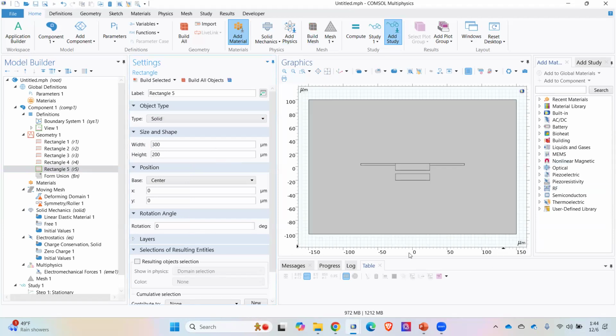If you make the air domain just 2 or 3 times the actual geometry, it will be fine. You can always check how your result is changing with different air domains. The total charge at the end boundary should be 0, so you have to consider that.